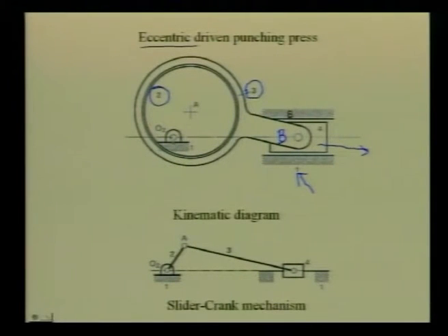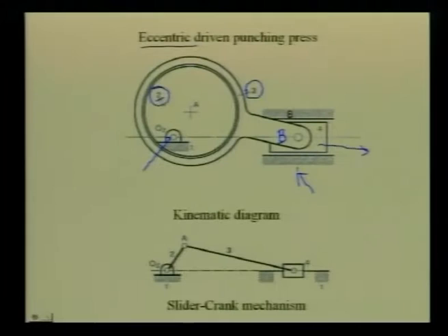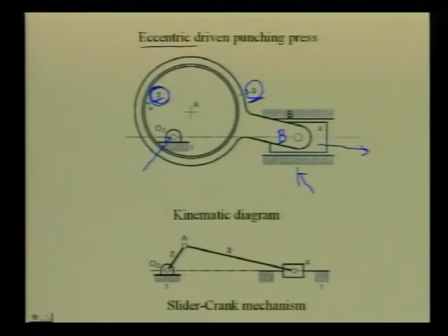This is the shaft which rotates the eccentric number 2. So, there is a revolute pair between the frame of the machine and this link number 2 at O2. The question is to determine what is the kinematic pair between these two links, namely 2 and 3. To decipher the kinematic pair, the best thing is to forget about all other connections and hold one of these two links, say link number 2, fixed, and try to move link number 3.